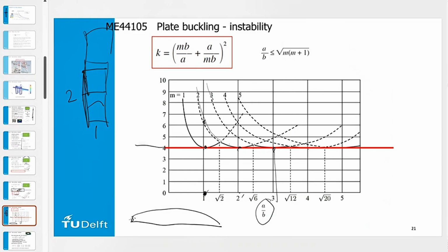So what you see is basically that the buckling risk does not depend on the length of my shape, but on the width. So if we have a certain width with an increase in the length, the only thing that happens is that the most critical buckling shape varies, but the buckling risk remains the same. And how is that? If we take, for example, 1, 2, 3, and 4, maybe that explains it better. If I have here a top, and then here a bottom, and here a top, and there a bottom, you see what happens.